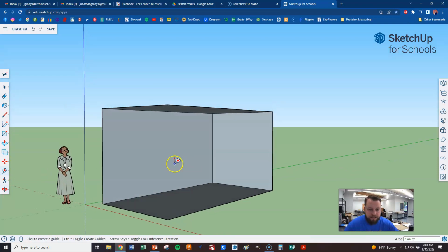And there's a lot of things a tape measure can do. The main purpose is it makes a parallel guideline. So if I want a vertical guideline going up and down like this, I can click on any vertical line that I want, because you're basically making a parallel line. So if I were to click right here, you can see that I'm dragging a parallel line out on the green axis, down the red axis, and I can't make it go up the blue because that's the direction it's parallel with. So since it's parallel with blue, I can only make it go green or red, okay?